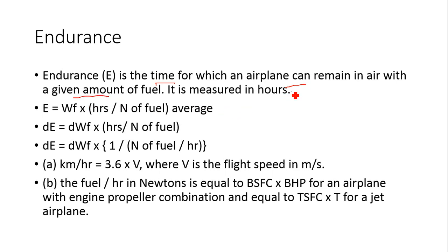And this thing is measured in hours. So here also, during its flying time in endurance, the weight of the fuel will change. It is directly proportional to the weight of the fuel, so that is equal to Wf into hours per newton of fuel. Simply we can say hours per newton of fuel. There it was kilometer per newton of fuel, here hours per newton of fuel.